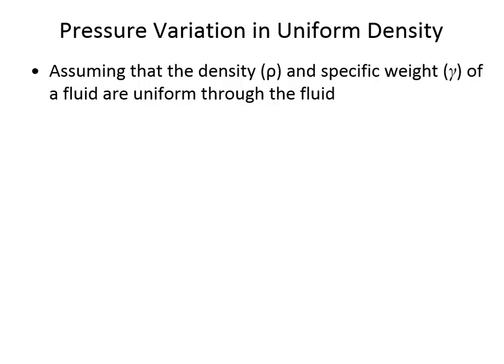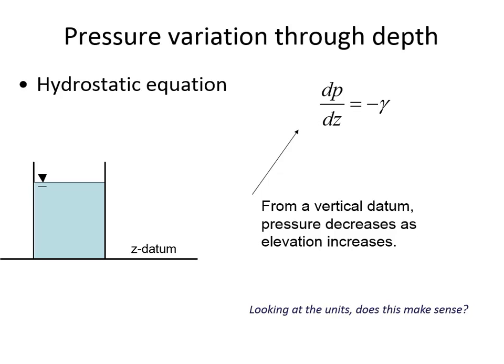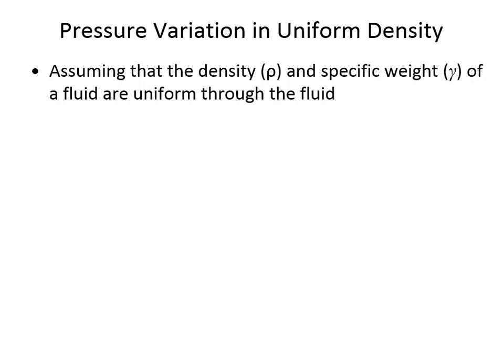We can use the hydrostatic equation to find out what is the pressure at some elevation, but the problem with applying that for too great of a vertical distance through a gas is that the density of the gas is lower at a higher elevation than it is at a lower elevation. In liquids, that's less of an issue.